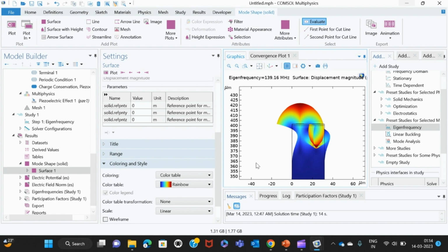So this is the Rayleigh wave. There are also shear horizontal waves, which you have to simulate for particular velocities of the zinc oxide. You will have to do some research and find out what the velocity is, and based on that you can fix your lambda, right? And then based on that you can find the eigenfrequency and simulate for that shear horizontal wave also. So this is the Rayleigh wave which we have simulated.